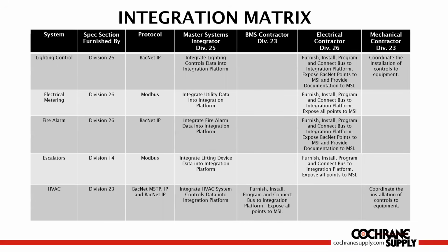This is what an integration matrix would look like. And I would advise that this matrix be put on every drawing where there's a large enough integration. So if you're integrating more than 2 disciplines, I would definitely put together a systems integration drawing. And if you're deploying an OT network or designing an OT network, I would definitely do a systems integration drawing. This is one of the things that I will put on there as an integration matrix.